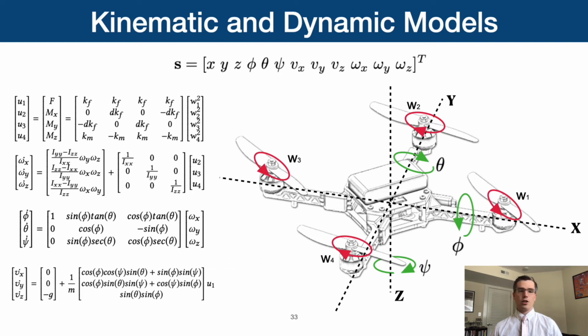On the left we show an example of this model, whose input is the rotation of the propellers and the outputs U1 to U4 represent the different forces on the body of the quadrotor. Using these forces we can update the angular velocities, which in turn can be used to update the attitude, which finally can update the velocity and subsequently the position. These kinematic and dynamic models are not uncommon and are used in many fields, including robotics, astrophysics, mechanical engineering, biomechanics, and game physics. Thus, they are widely available for a wide range of robotic vehicles.